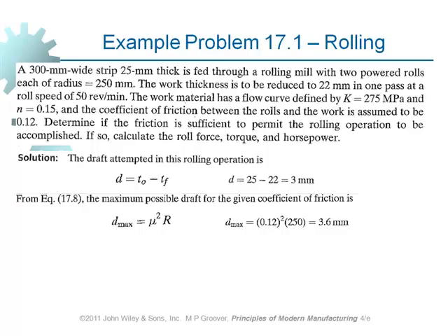The reason is that we've got to see what we want to achieve, besides the magnitude of the deformation. If you want to achieve a thickness of, say, 2 millimeters, then you cannot do it in one pass. This equation is telling you. So you've got to take 2 passes and achieve the magnitude of the deformation in 2 passes, instead of one big pass and one slight deformation. It's better to make it something in between.